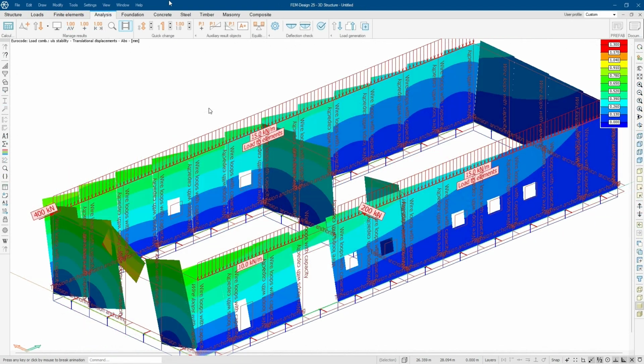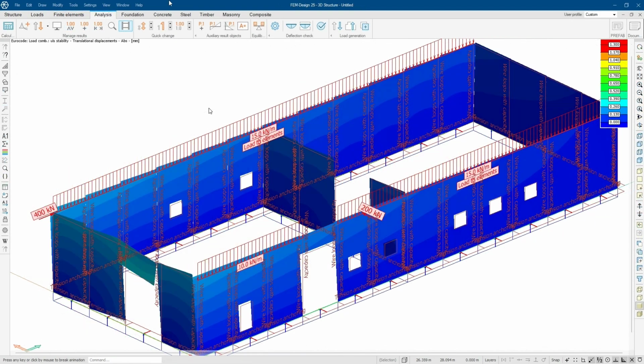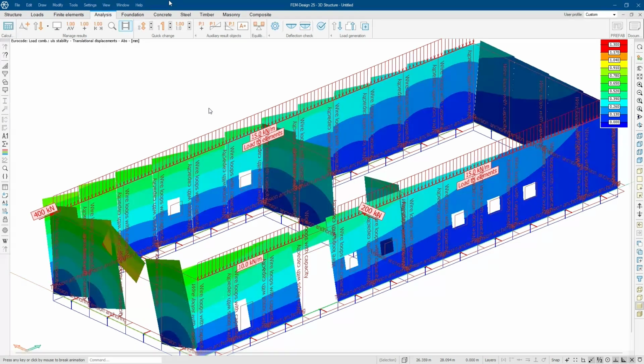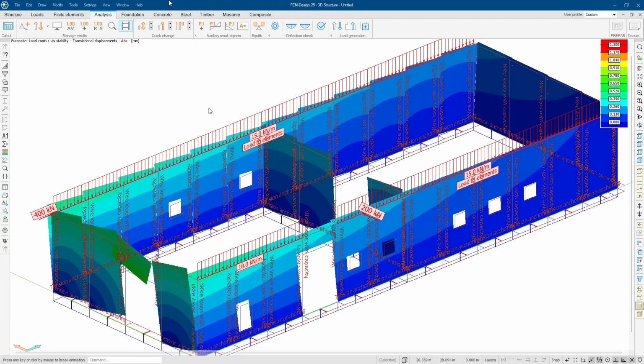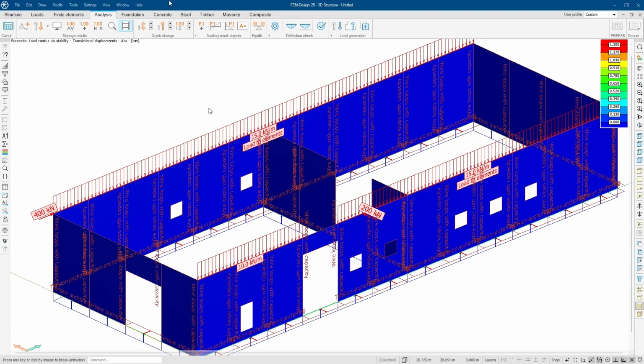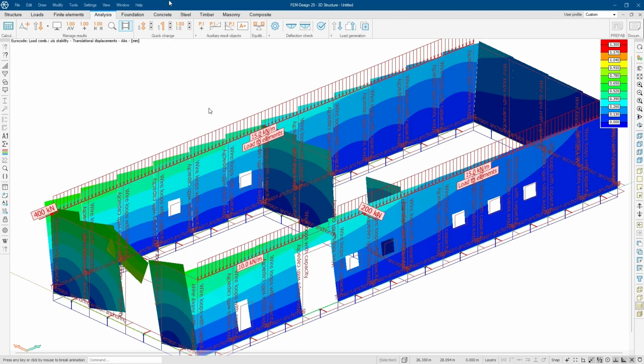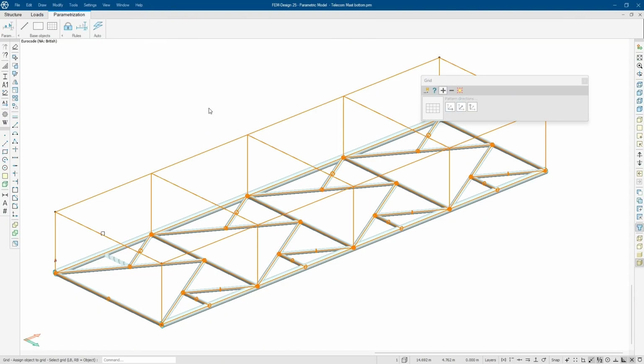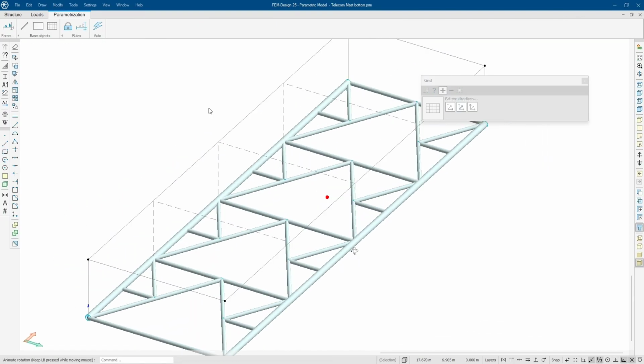So it's a nonlinear calculation, and you can see that concrete has a different spring value on tensile side and compression side. So you get a really realistic model really fast, and you can calculate the overturning of concrete element wall system really fast if you put it in the parametric block, and also those edge properties are copied.